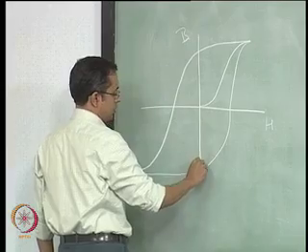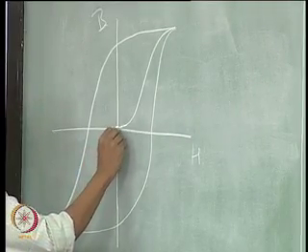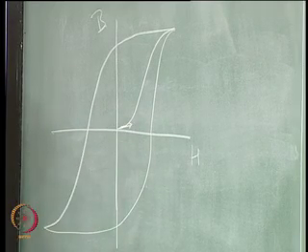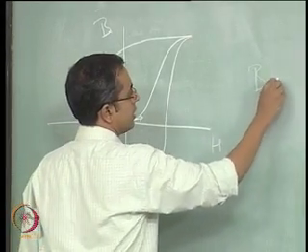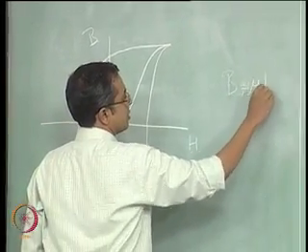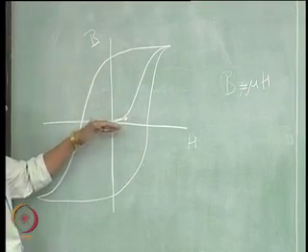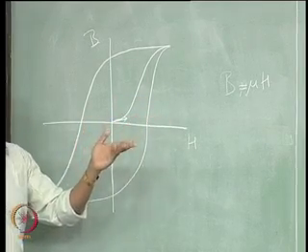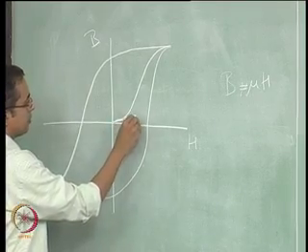So this is the behavior that you will see, and again you can write permeability here, which is simply, if you write B is mu times H, right. So clearly at each place, B versus H, if you look at the slope for B versus H, that slope is what the mu is. That slope is varying, and so this is called mu I, or the initial permeability.